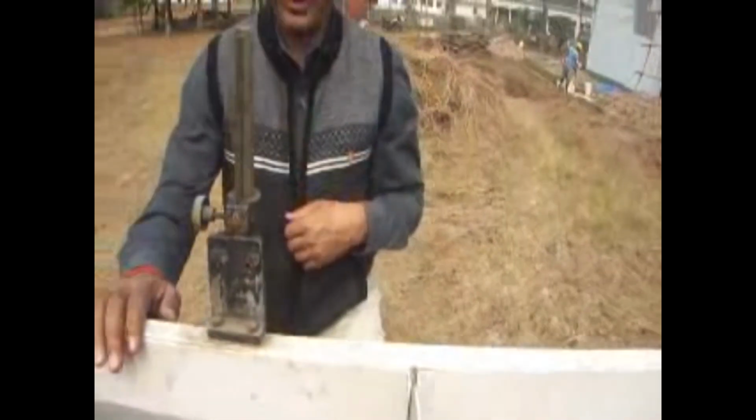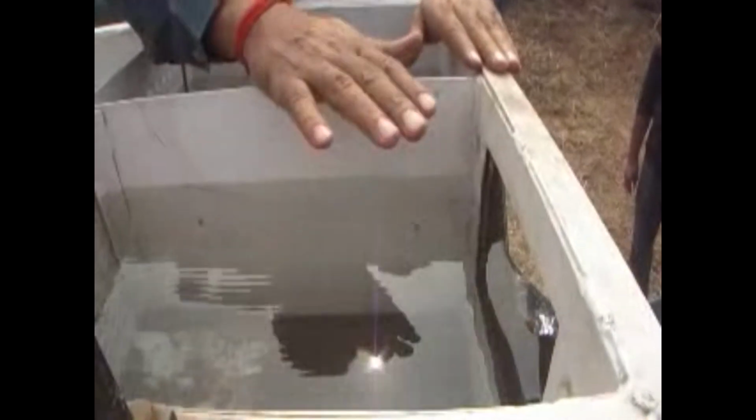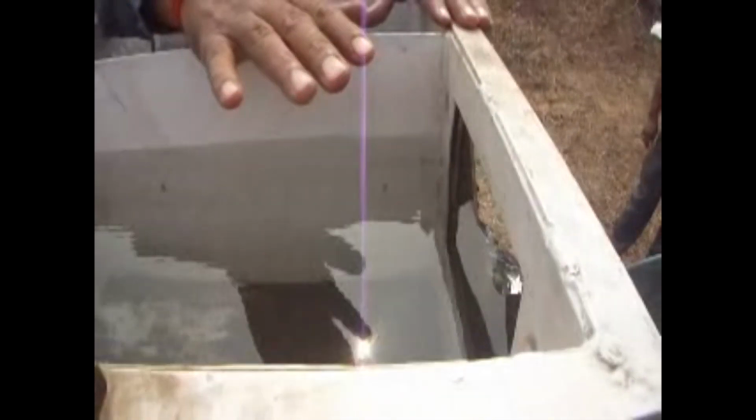The head of water flowing over the crest has now stabilized. So we need to measure what the head is. But the level of the water at the tip, just over the crest, we will measure at the last when we finish this experiment.